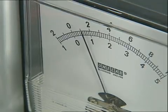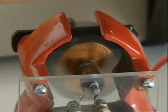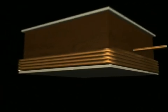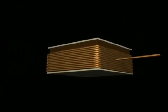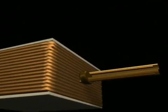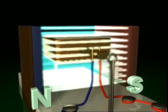The interaction between a magnet and a current-carrying conducting wire can result in a continuous rotating motion. A current-carrying conducting wire will experience magnetic force in a magnetic field. Wind the wire around a rectangular former to form a rectangular coil and connect both ends of the wire to a power supply. Place the coil between the two poles of the magnet.